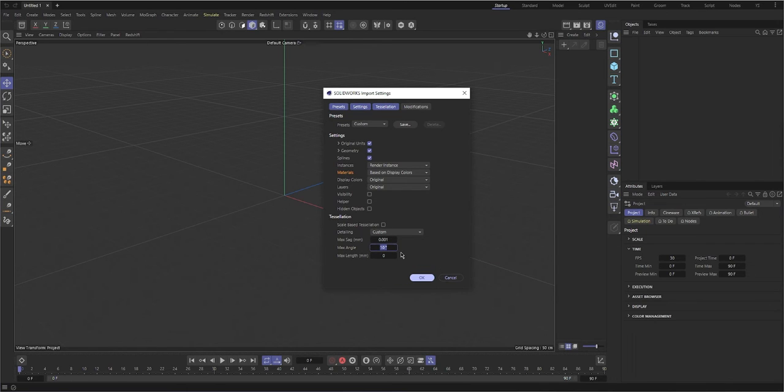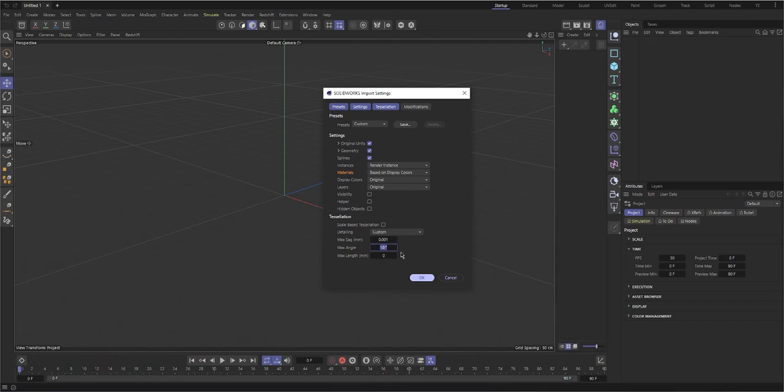Now, this will again depend massively on how much system memory you have, and also when you come to rendering in Redshift, how much video memory you have. So tweak these values with a bit of trial and error. If you experience lag or crashes, increase this number so that you aren't dealing with such a high number of polygons, but just know that you will have a less detailed model. I know that my workstation can handle 1 degree, so I'm going to set it to exactly that.